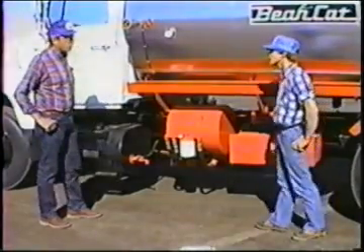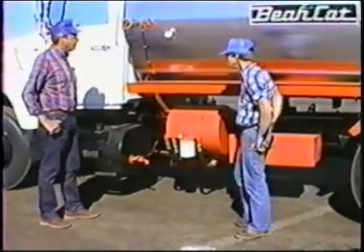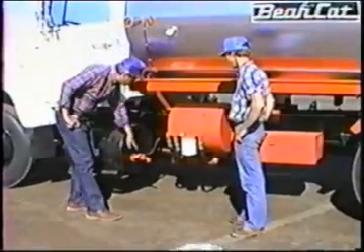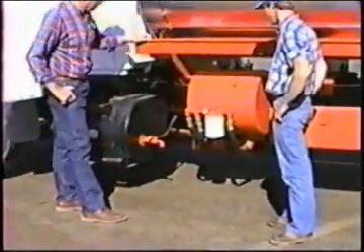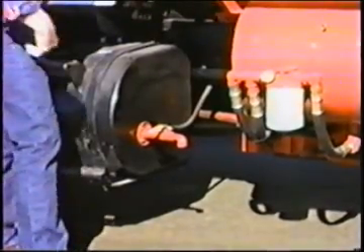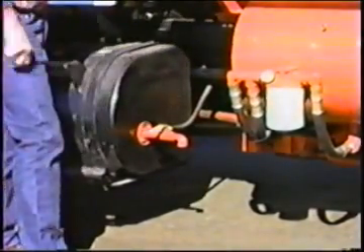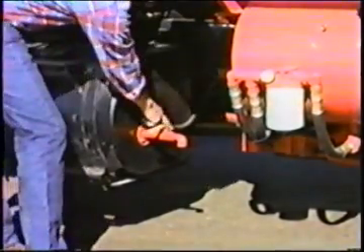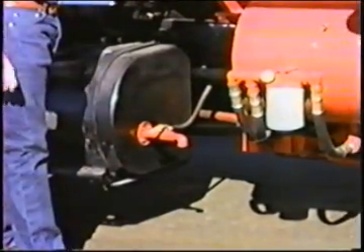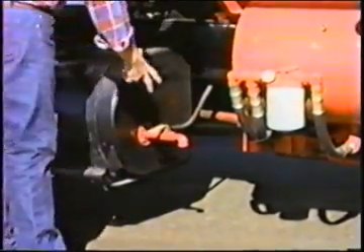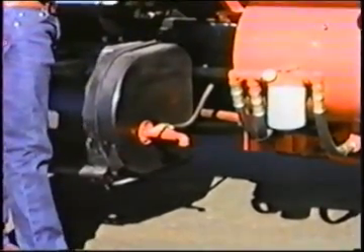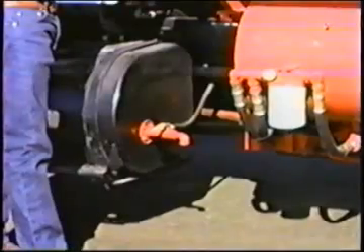Bill, there's a few things around the outside of the truck that I want to point out, just mechanical items. Down here on the truck fuel tank is a fuel tap. We tap diesel right out of the truck tank. The valve here is for filling your bucket. The line that goes out and goes to the back of the truck, that's the fuel to the diesel burner. We mount that fuel tap 8 inches off of the floor of the tank, so there's no way that you can use up all of the truck fuel when you're heating.